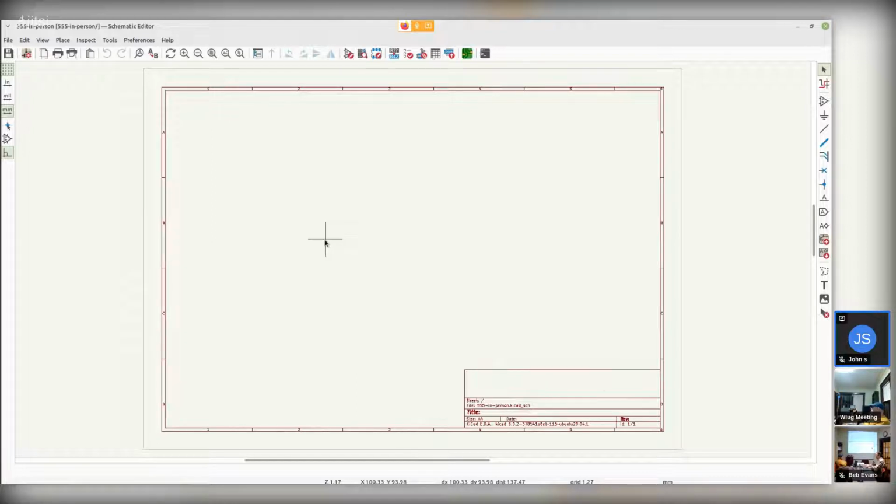I could change it. I don't know how to do it quickly. Yeah, the one thing I do with the preferences is I left the origin the same, but I set the measurement to millimeters. The reason for that is that once I get the Gerber files, I want to load them into G-code so that my milling machine can mill out traces.